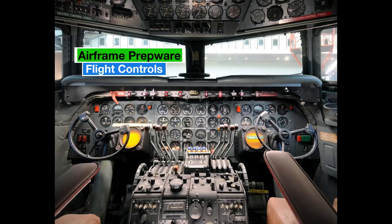Proper wing twist in a sheet metal constructed wing can usually be checked by utilizing a bubble level and special fixtures described by the manufacturer. Where would you find precise information to perform a symmetry alignment check for a particular aircraft? Aircraft Service or Maintenance Manual.